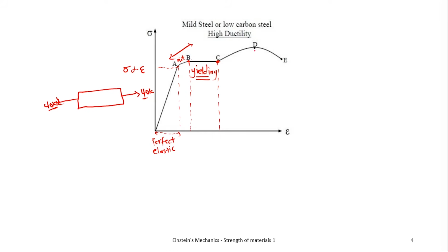From C to D, what happens is that it is going to what? You see, the stress is now increasing. It is going to elongate, but stress is going to increase, and strain is also going to what? Increase. So at D, that's what we call the ultimate stress. This was all the test was going to tell us. Ultimate stress, meaning the overall strength of the material I'm testing was maybe 40 kilonewton.